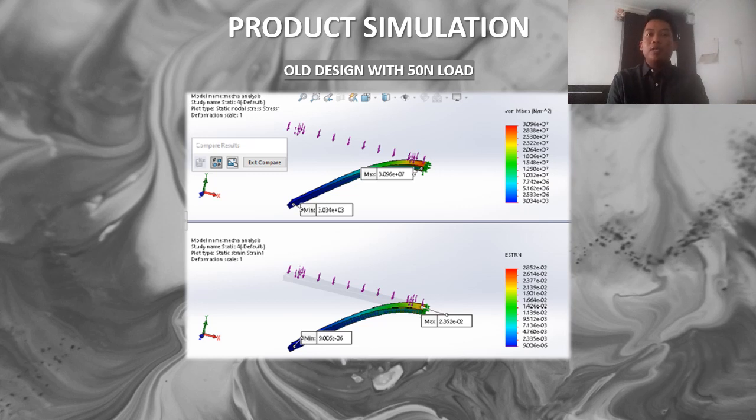And now I will explain about the product simulation. We compare the simulation for the old design with the new design that we enhanced. For the old design, we tested the product with a 50 Newton load, and as we can see here, the product underwent major deformation and displacement at the hinge part of the handle. We consider it crucial to improve the function at this part, because it would cause a major malfunction to the product if it continued.